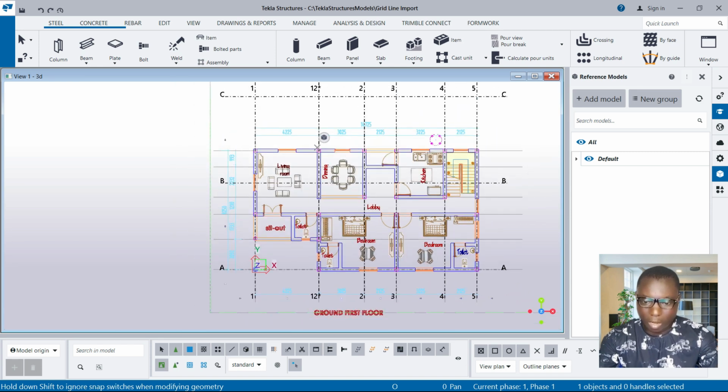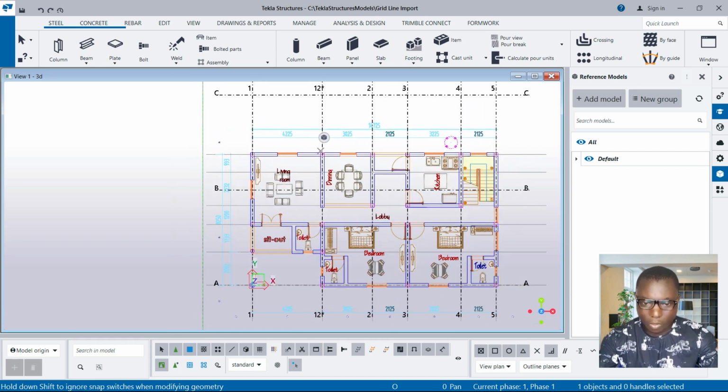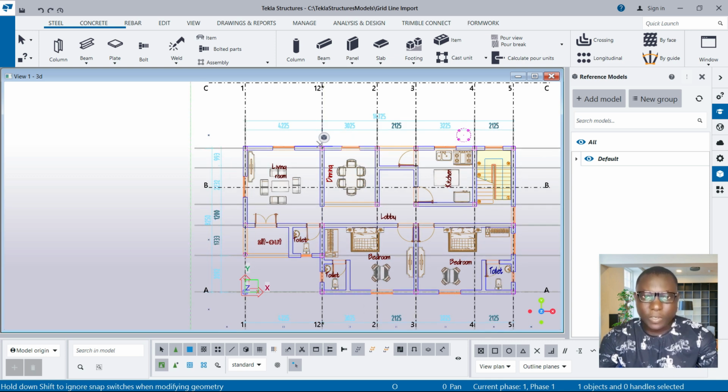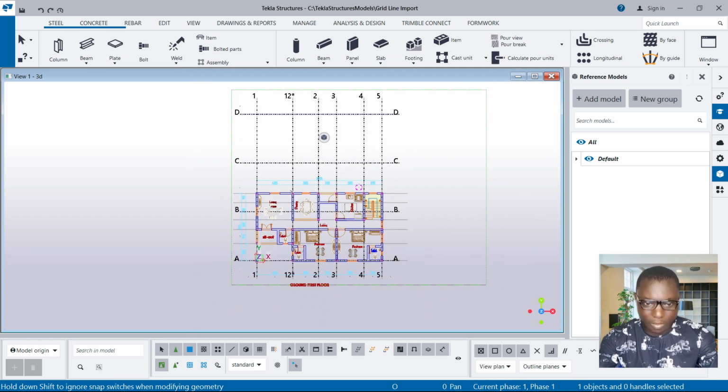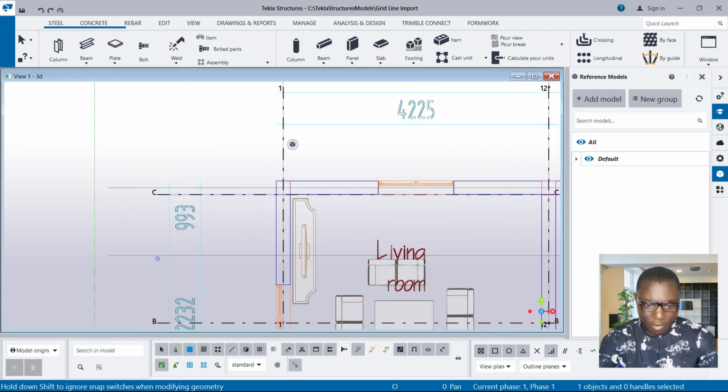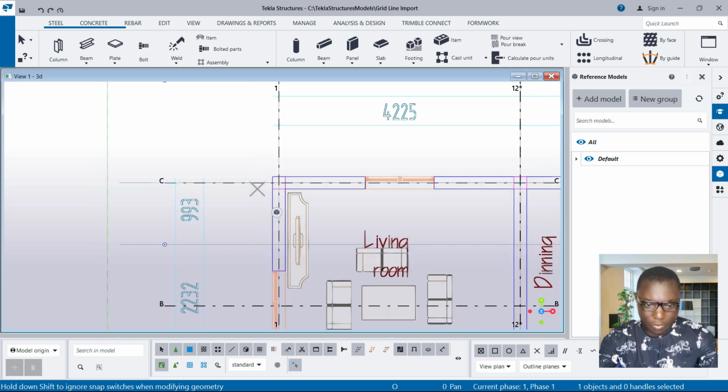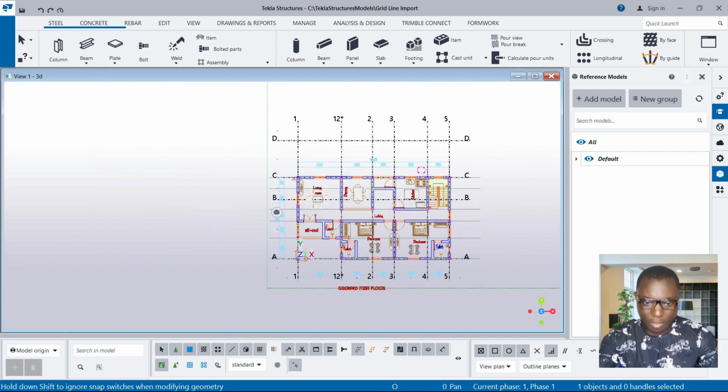So in the vertical grid lines, we have done with the merging successfully. Then in the horizontal grid line, I will come over to the first one right there, click and pull it down to these provisions and come close to check it's not well placed. So align it with that first one.